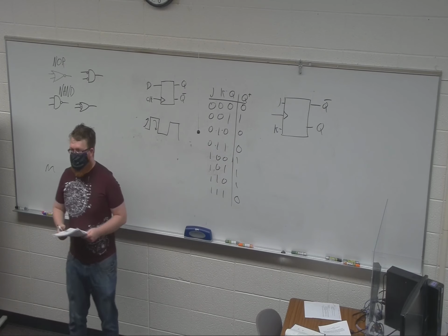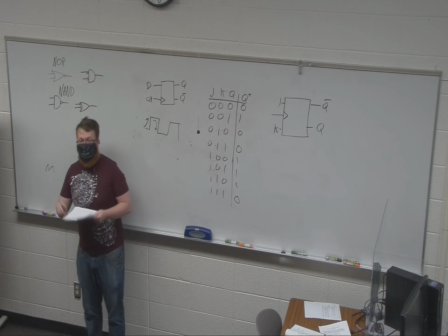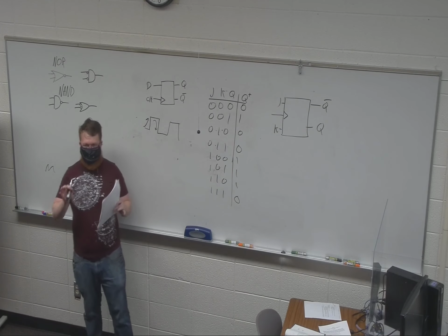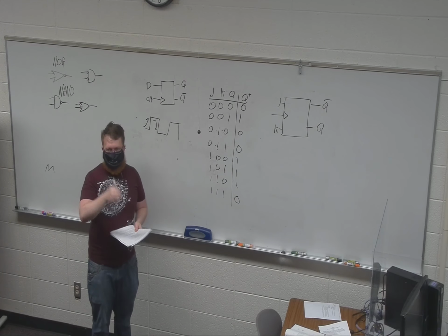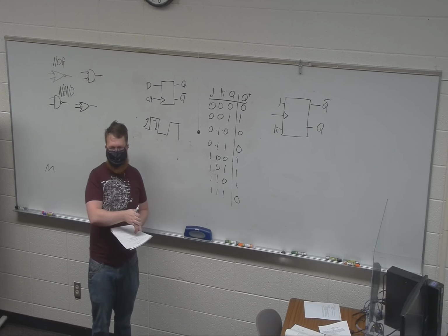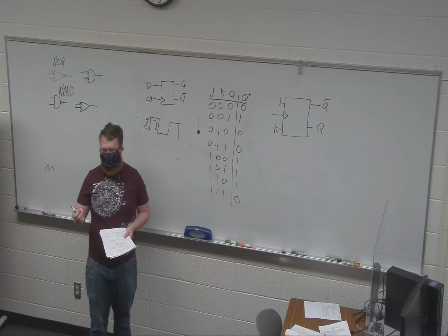What is the difference between a Mealy and a Moore state machine? One's output just depends on state, and one has state and input dependent output. Yes. So the Mealy cares about both the current state and the inputs. The Moore state machine only cares about what state it's in.